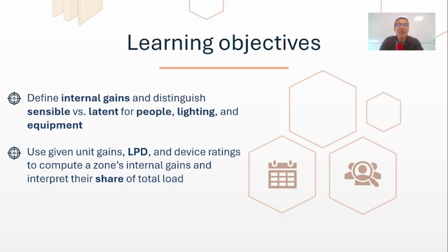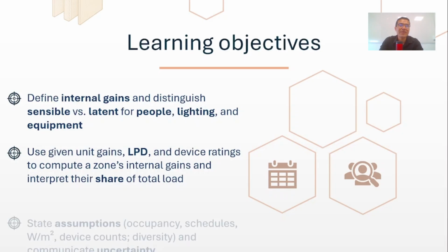Second, we'll give you the skill to compute internal gains. You'll learn how to take real-world data like unit gains for people, lighting power density, and equipment ratings and turn them into concrete numbers you can use for your calculations. You'll also learn how to interpret these numbers to understand which component has the largest impact on your building's load.